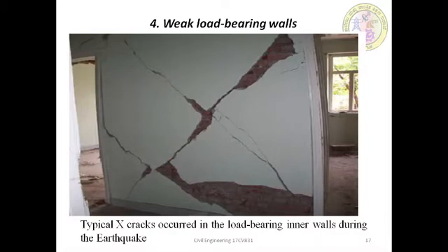Excessive bending and shear may produce in-plane failures depending on the aspect ratio of the unreinforced masonry elements. Many masonry buildings sustained very significant damage to the walls in the form of X, that is double diagonal shear cracking, a typical failure of weak unreinforced masonry, which is shown in the figure as unreinforced walls in shear.